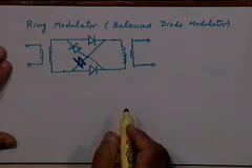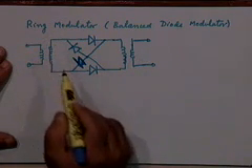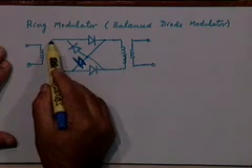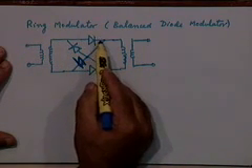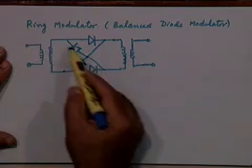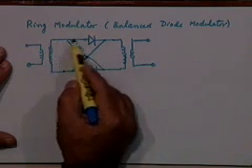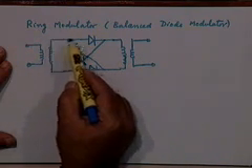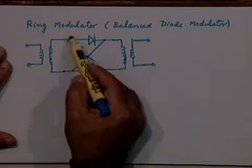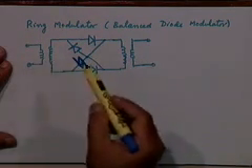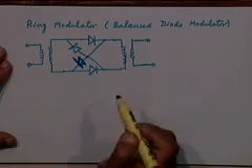So this is a balanced modulator. It is also called a ring modulator. The reason being that these diodes all face in the same direction. As you trace the diodes, they are all pointed in the same direction, right. So if you go along these diodes, they form a ring in some sense. So we call it a ring modulator, right.